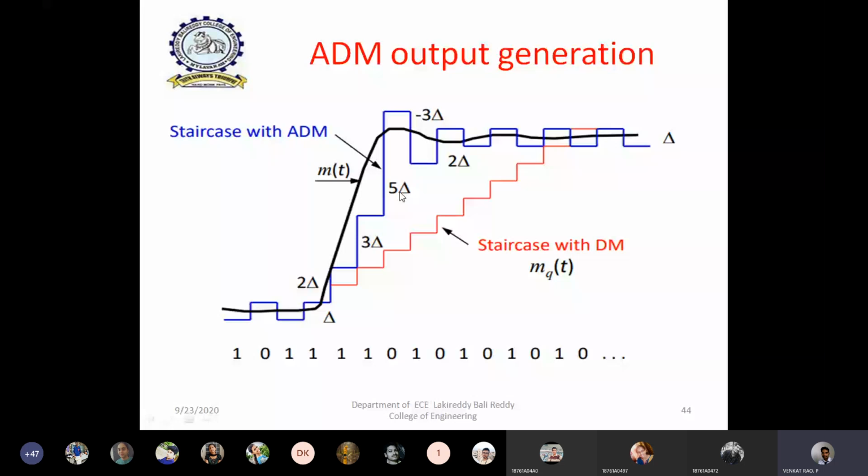Similarly, during this portion, even though the input has very small variation, that means almost no variation in the input signal, the staircase waveform is still approximated using some step size. If you observe this height, even though it is small, it seems very high compared to the input signal variation, because the input variation is almost zero, but we are approximating with some height. Again, we observe a small gap during this portion between input and output. That gap is called granular noise.